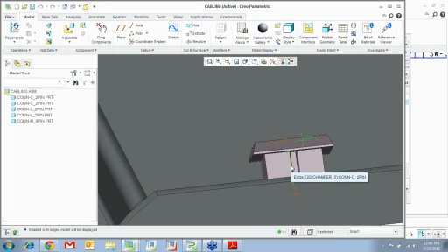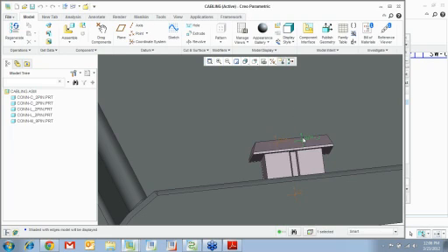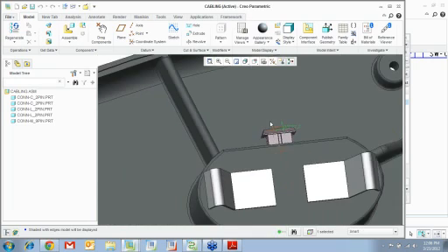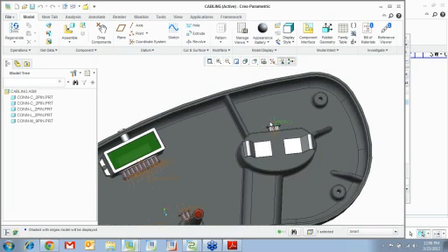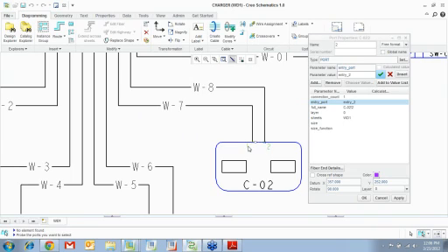See that? Entry_2 coordinate system. So the wire's going to go into that particular coordinate system, and you can see the Z is pointing outside, right? So the wire's going to come in like that. That is how I am actually mapping each component to a symbol and each coordinate system to a port. Okay,